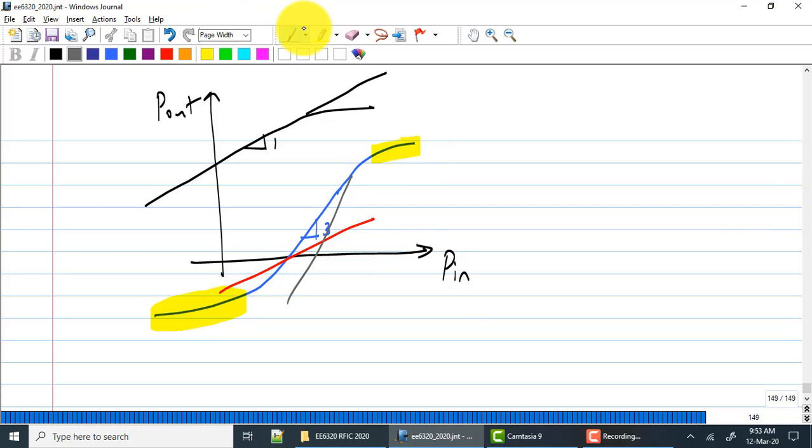Number two, you might be able to see gain expansion in both the fundamental curve as well as the third order curve. You will especially see this if you are operating at, you remember we discussed, right? There is a certain range of VGS minus VT over which you can see gain expansion when the sign changes.